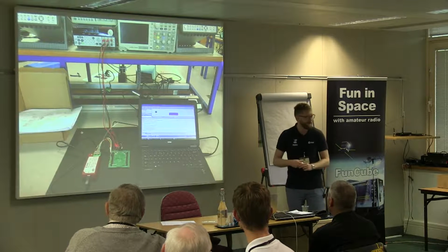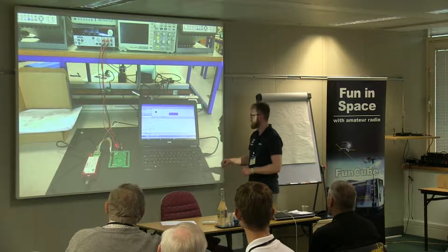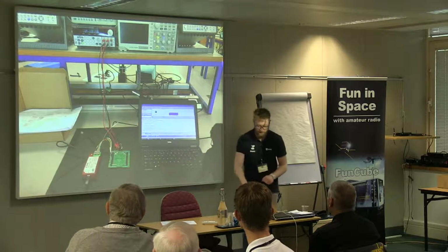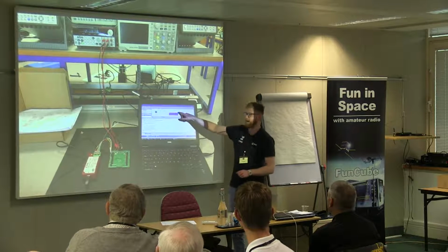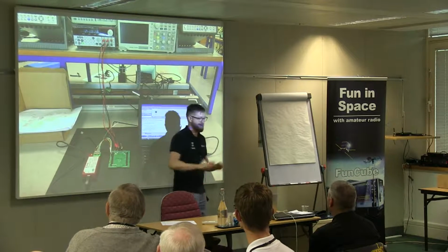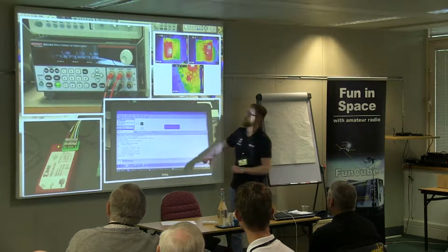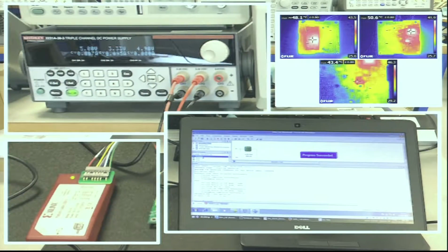This was a good day. Okay, there have been bad days. We'll concentrate on the good days that I wanted to highlight in this picture. One, it says program success, green lights through the JTAG, really low power. Let's have a zoom in. What we'll actually have there is on 3v3, we're drawing 95 milliamps, and on 5 volt, we're drawing 7 milliamps.